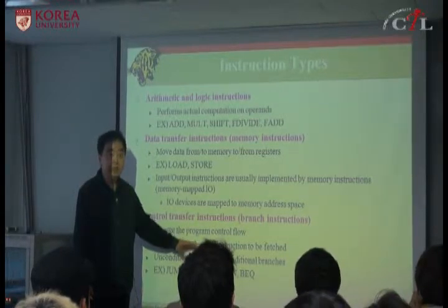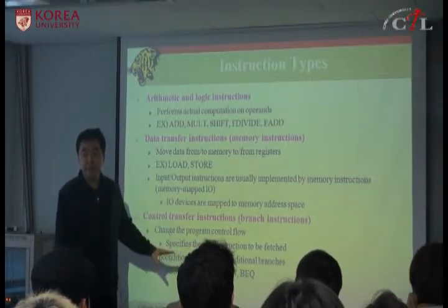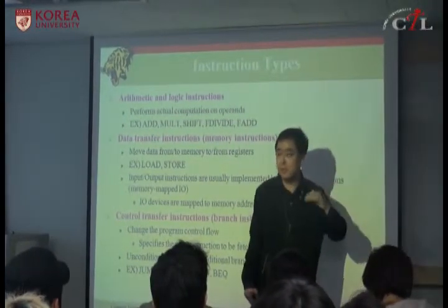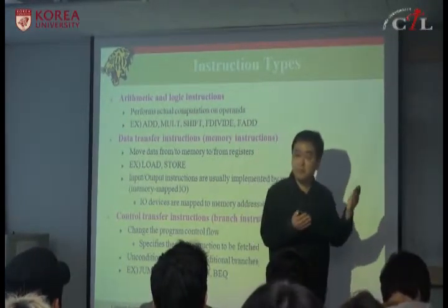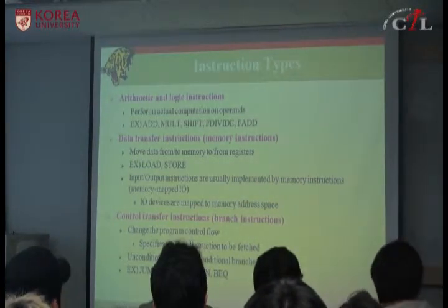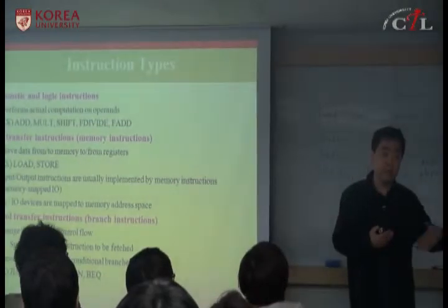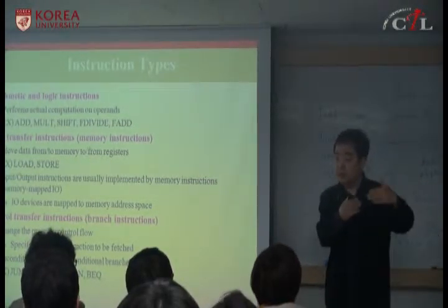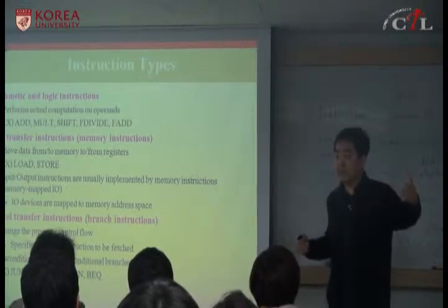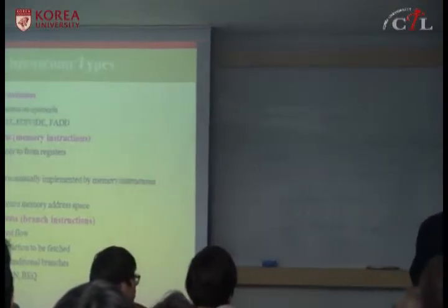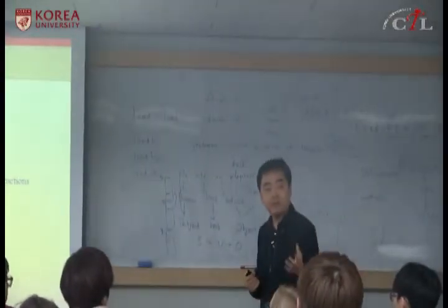Without a branch instruction, you just keep fetching one instruction at a time sequentially. Because an instruction is 4 bytes in a MIPS processor, you just need to increment your program counter by 4, because it points to the next instruction, as instructions are stored sequentially. So by adding 4 to your address, you can fetch the next instruction one at a time.